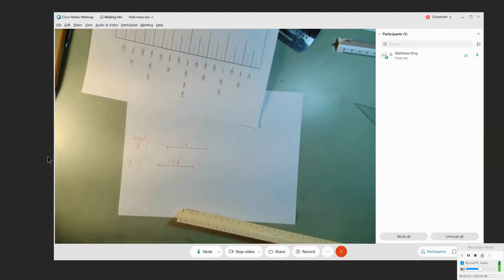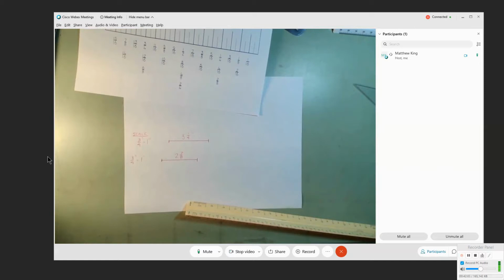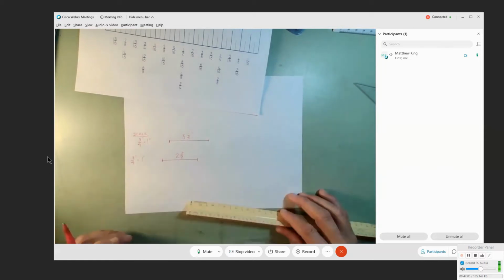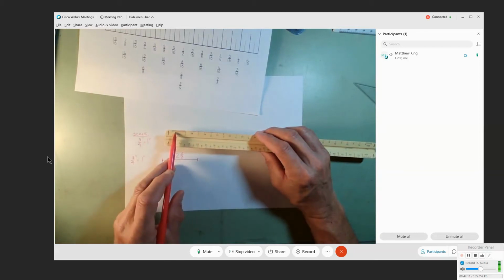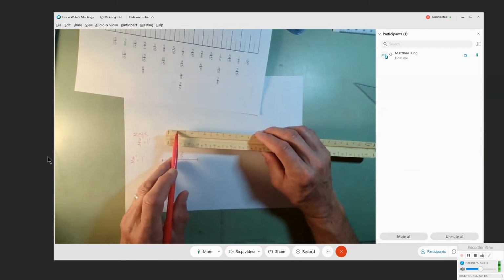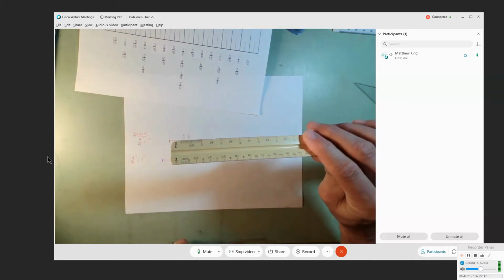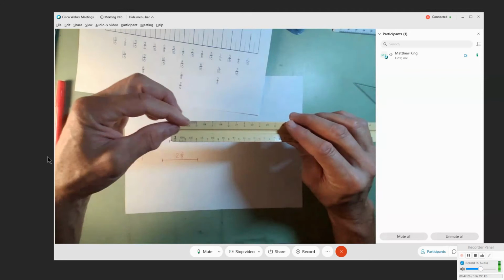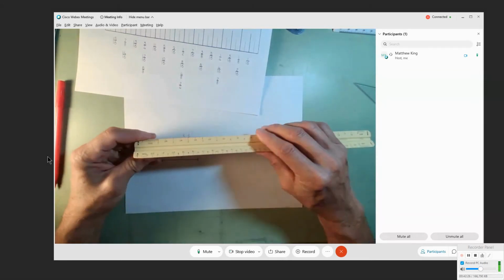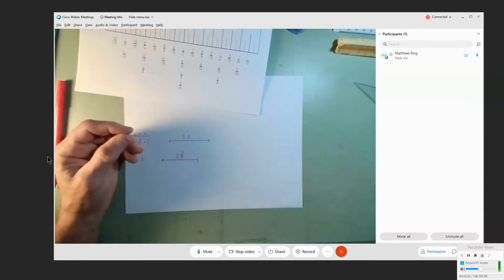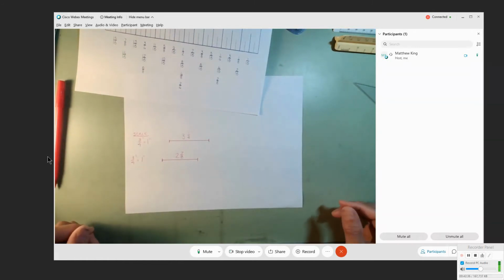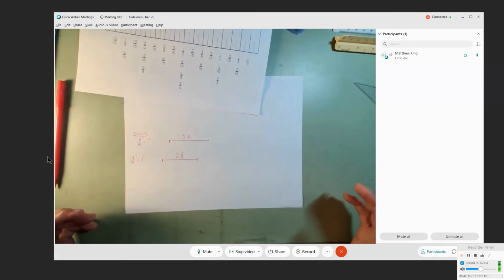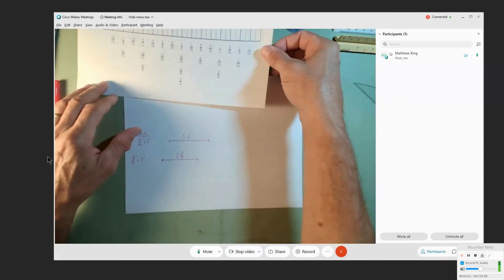So that is what we have to get used to immediately. I mean, you're going to have a homework assignment that you're going to have to draw at 3/4 size, and you simply lay out all your measurements on this scale. And anything that's a fraction of an inch, you've got to find over on this graduated area here. And that's a skill unto itself, and that skill can apply to any scale on any ruler, so to speak. Okay, so I know I've gone over 2 examples, and that hardly makes us experts, but like I said, you're going to have to take that knowledge and you're going to have to grind a way to figure that out.